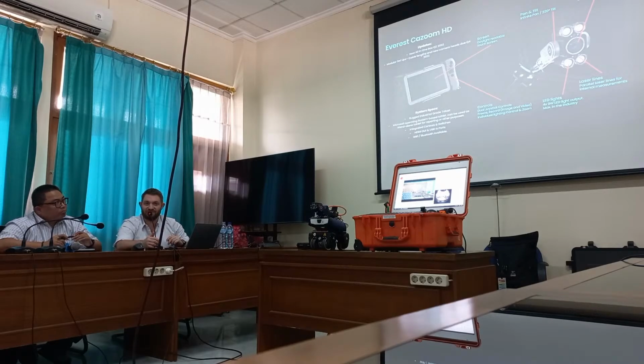We've got laser lines for doing surface measurement. So if we've seen an area or we want to roughly work out how big that area is, we can take an approximate size estimation. Now these are not for doing depth measurements of pits or cracks or surface profile. It is an approximate area surface measurement only in a 2D plane. So if your vessel's curved, it's not going to follow the curve of the vessel, it's only going to go from point A to point B. So you might be out by a little bit, but you'll get a rough size estimation of what you're looking at.